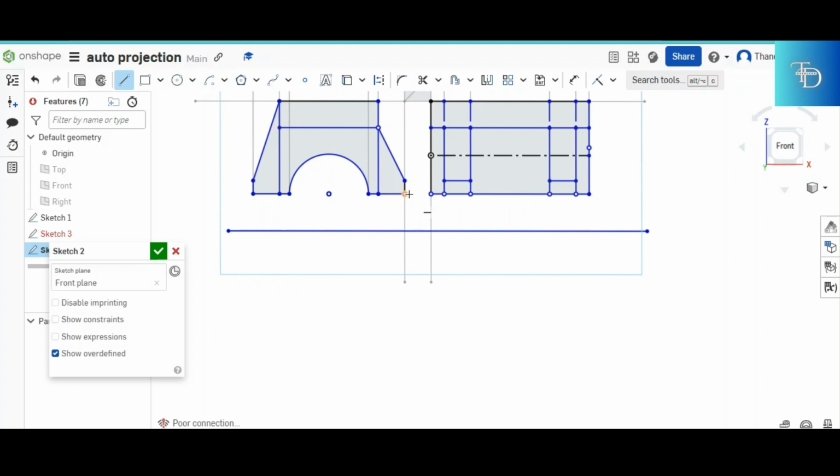It's going to start where the front view started, the special corner, the starting point of the front view, going downwards at an angle of 45 degrees to the horizontal. This is how you were going to do it. Then you transfer this point right there, it goes that way, goes straight down to the 45, it goes that way. When you are done with that, you come to the front, and they go straight down from the front. And then you produce your top view from that position right there.